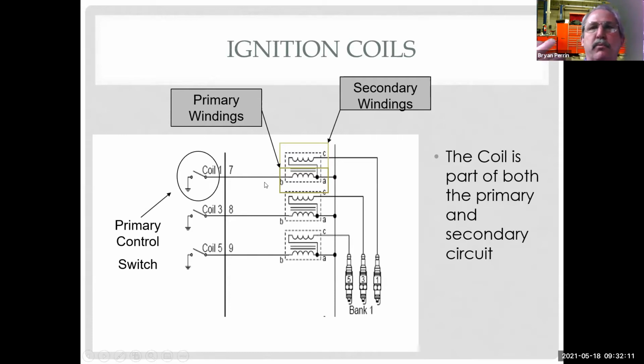We're going to pulse width modulate this if we are controlling it directly by a computer, because the amount of dwell time or saturation time is going to change, and how often I do it has to change. So that's the definition of pulse width modulation. Changes frequency and changes the amount of on time.